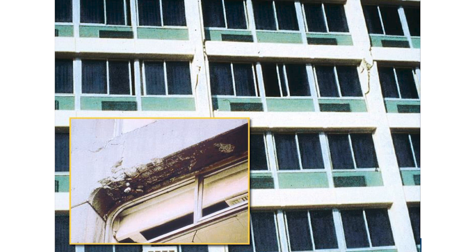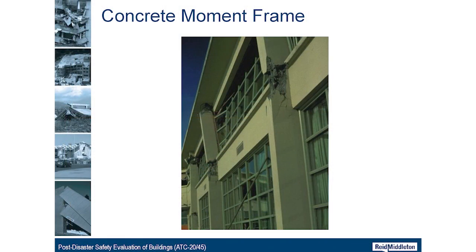So scale 1 to 10, vertical load carrying capacity. I think I heard a 1 and an 8 and a 7. We got a large spread here. Our standard deviation is significant. Lower. Yeah, inverse: 10 is good, 1 is bad, so a 2 instead of 8. Because those cracks are through those columns, it's intuitively very concerning.